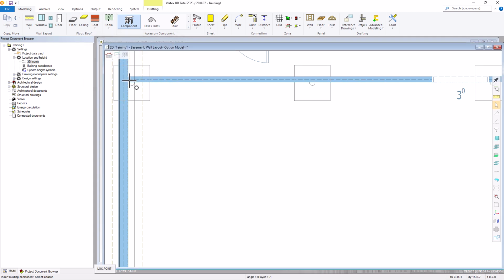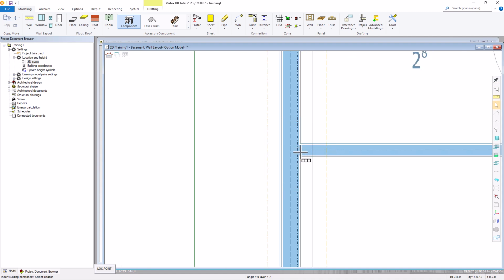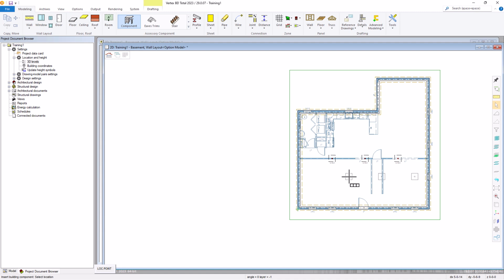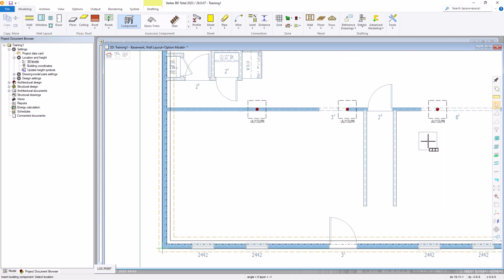And now we're going to zoom in, find the endpoint of that interior wall. We're going to cue, hit the U key to move it over to the right, and type in 10 feet. Bring that over so you can see 10 feet, and enter. If I zoom out, you see now we have 3 columns equally spaced 10 feet apart. I'm going to hit escape to cancel the command.